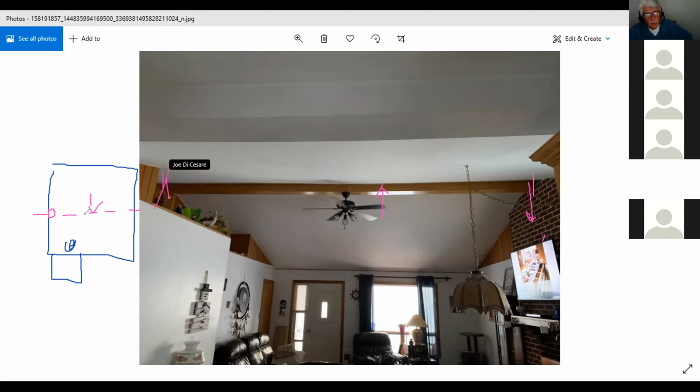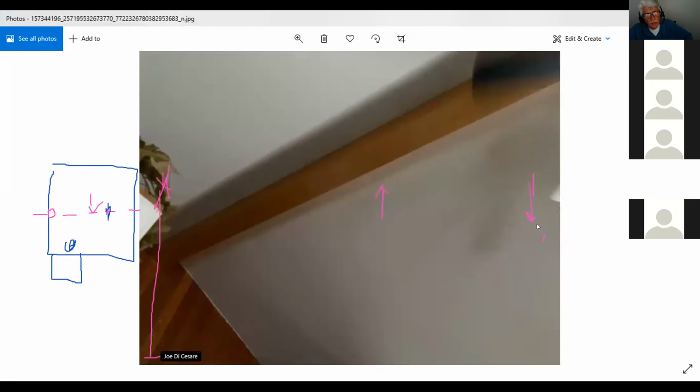Where is this point here on your plan? This one, this point here, where is that point? It would be approximately here. Okay, so that's why you have to be careful, because if it's here, there's a column in there. There has to be a column in there, Brandon. You understand? So like here, there's a column that goes down. It probably goes and sits on top of the beam. Like it just goes in there, and behind this place here, that's the closet space.